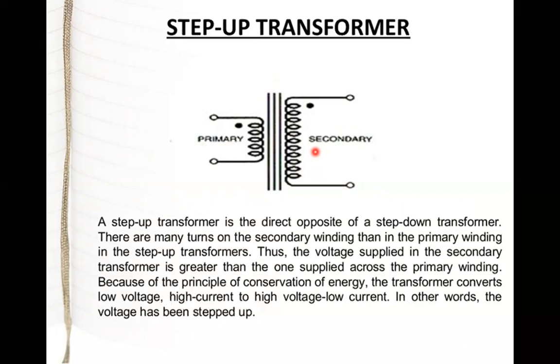For example, the same 220 volts can be multiplied 10 times using a high number of turns on the secondary coil. So here the 220 volts is the input, whereas the output is 2200 volts, because we have multiplied the input voltage by 10 times, and that voltage will be sufficient for 10 families residing in an apartment. So that is the basic application of a step up transformer.